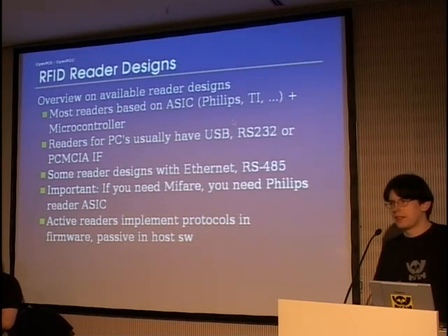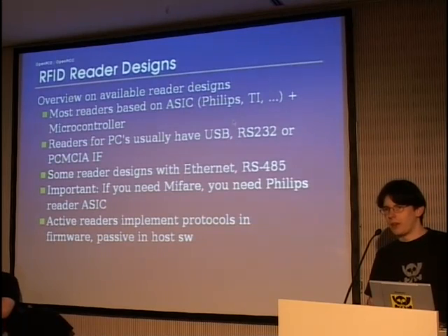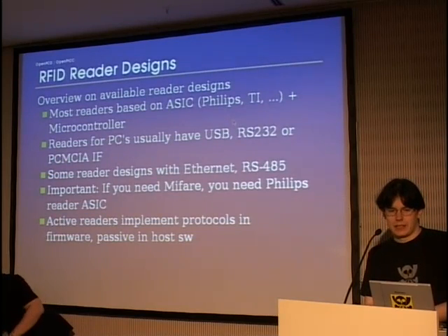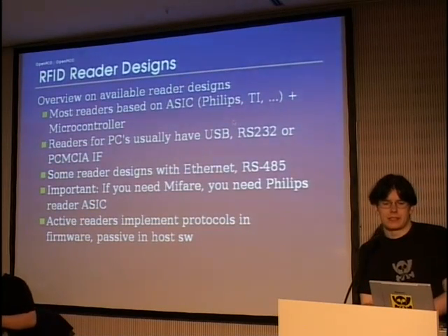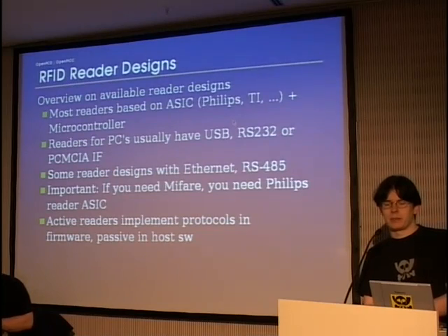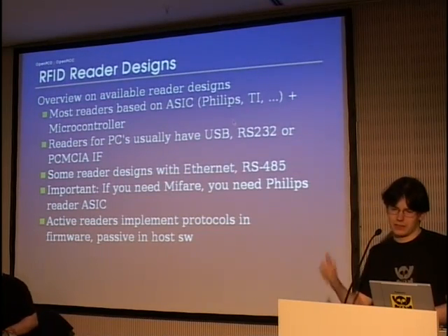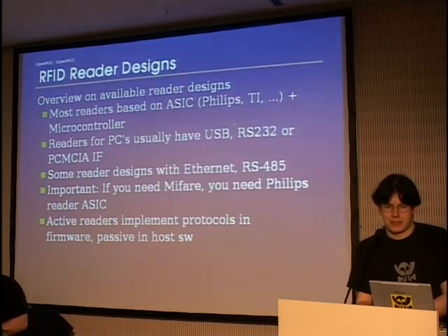So if you look at existing RFID reader designs, as in commercially available products, for the 13.56 megahertz RFID standards, then most of these readers you will find are based on an ASIC design from Philips, most likely. Well, now it's NXP actually. Philips Semiconductors has been renamed.